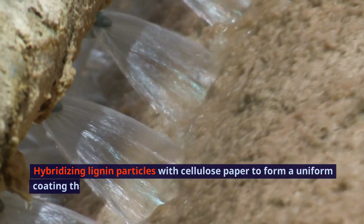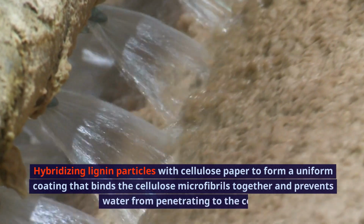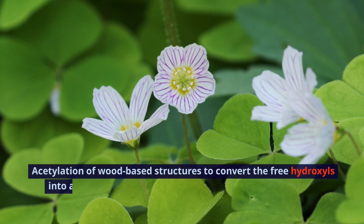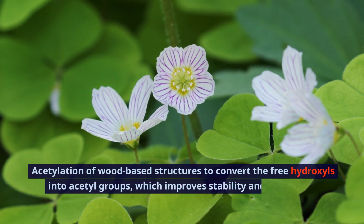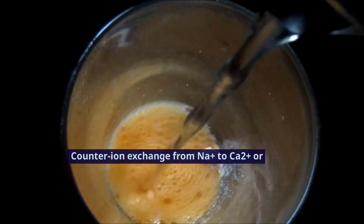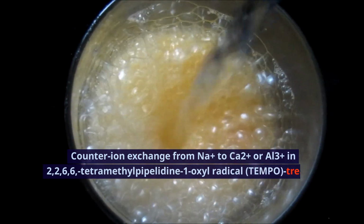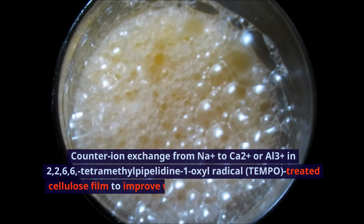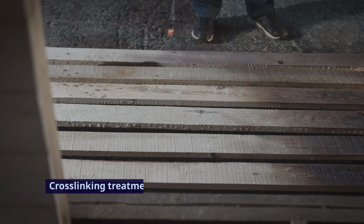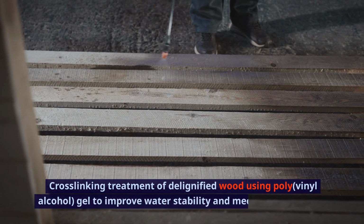uniform coating that binds the cellulose microfibrils together and prevents water from penetrating to the core, acetylation of wood-based structures to convert the free hydroxyls into acetyl groups, which improves stability and anti-fouling properties, counter-ion exchange from Na+ to Ca2+ or La3+, and 2,2,6,6-tetramethylpiperidine 1-oxyl radical, TEMPO, treated cellulose film to improve water stability and oxygen barrier properties. Cross-linking treatment of delignified wood using polyvinyl alcohol gel to improve water stability and mechanical strength.